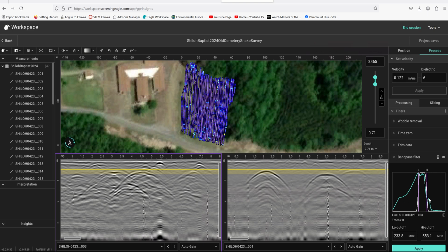There's a little interesting peak here going on at number 3. So it looks like I can come down to 187 here if I want to capture all of that. But in my experience, again, I'm going to probably leave it around 200 to 500, 200 to 600. So about 200 megahertz above, 200 megahertz below is fine. I've even brought that in even more.